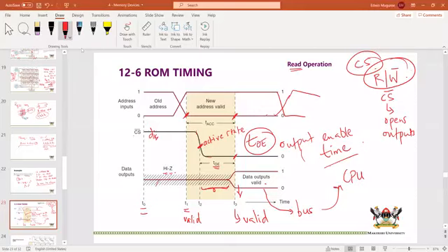I like them a lot because they really tell you that this person understands the procedure. And I ask them a lot, so really take them seriously. We are going to see more complicated timing diagrams where there are more commands, but here it's just the address, the chip select, and then the output.